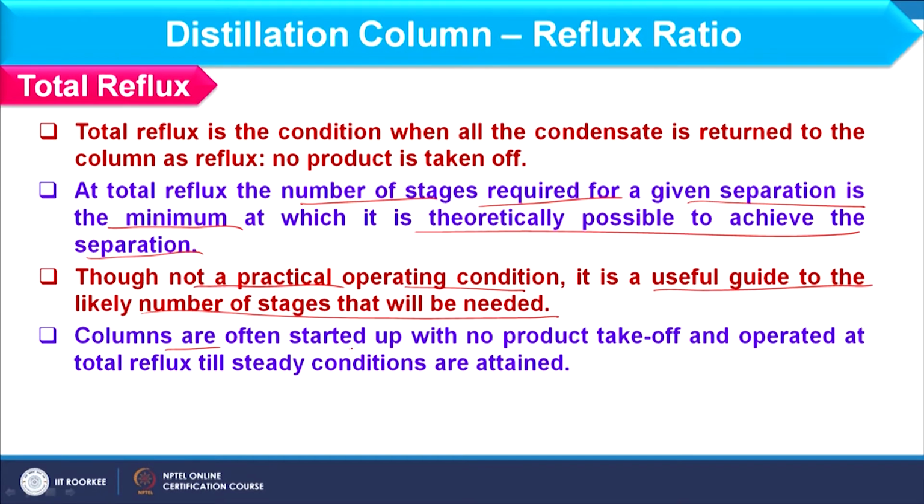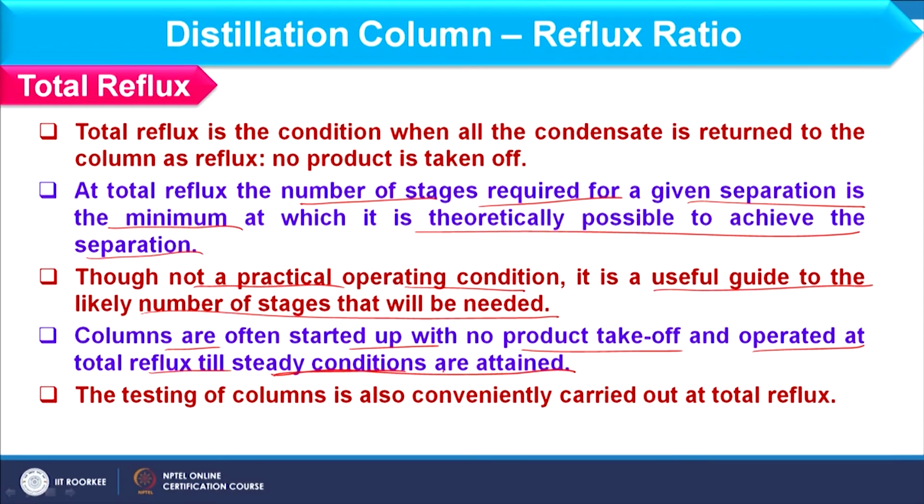Columns are often started up with no product takeoff and operated at total reflux till steady state conditions are attained. That also happens, but only at the start of the process, not after that. And testing of the column is also conveniently carried out at total reflux condition.